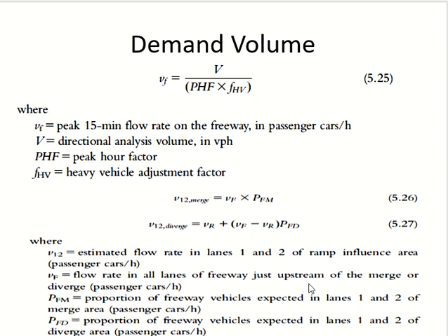So you have to include the ramp as well, because people are going where? To the ramp, right? Whoever wants to go on the ramp is where? On the freeway. So that's why these two. Because ramp volume is already on the freeway right now. It will go out from the ramp later when it reaches the ramp, but right now it is on the freeway.